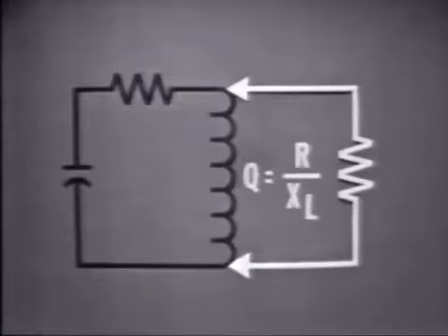However, there is another quality factor that concerns external circuit resistance, and in this case, the resistance should be high. In other words, the amplifier connected to the frequency determining device should offer maximum impedance to the tank. Even then, there will be some energy loss to the external load, which must be regained by increasing the feedback.